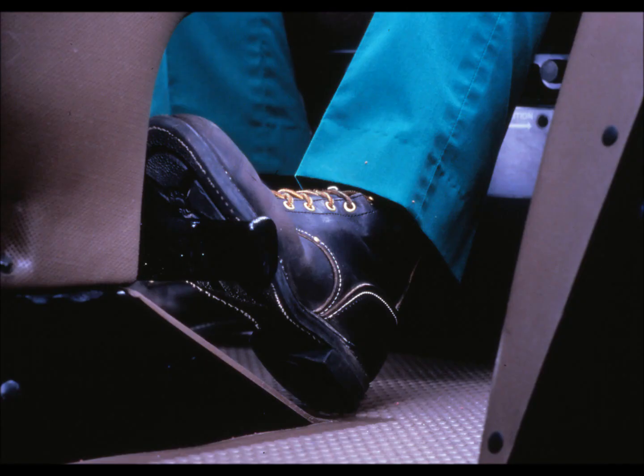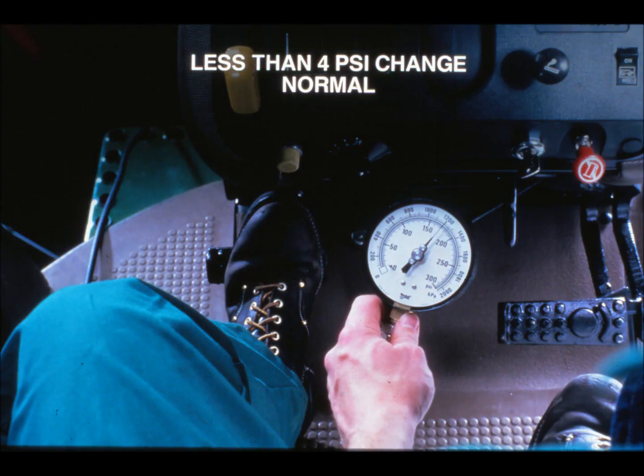Run the engine at 1,000 RPM. Engage and disengage the traction clutch pedal. As you engage and disengage the clutch pedal, record the clutch pressure at the traction clutch valve housing. If the pressure changes less than 4 psi, the system is normal. If the pressure changes more than 4 psi, there is leakage in a transmission element circuit.